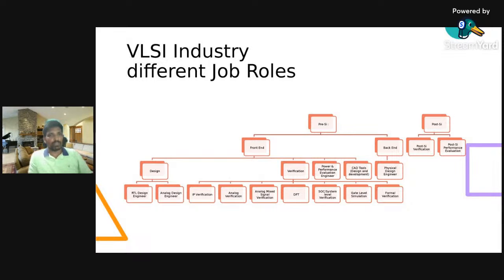Then there is a different type of verification nowadays. It's becoming more of a trend that each company is involved there, and we call it formal verification. So we have formal tools. We use heavily the SVA, SystemVerilog assertions, and it can be used both as assume as well as assert, to make sure that instead of writing the stimuli, we allow the stimuli to be generated only from the tool, and the tool will give us the failures if we have any in the design. So that's more from the verification side.